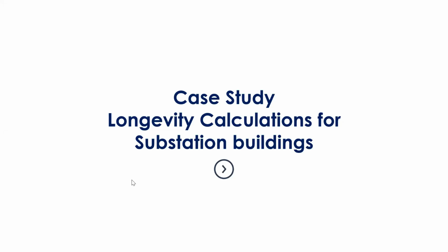Next question is, what is the acceptance deviation or tolerance limit in percentage terms with respect to the estimated service life versus the reference or the design service life, let's say a marine structure, such as a jetty trestle, as most of these structures have a life of, let's say, 25 to 30 years. See, for offshore structures, there is a separate mechanism which is API 2A. Then other extended standards are there.